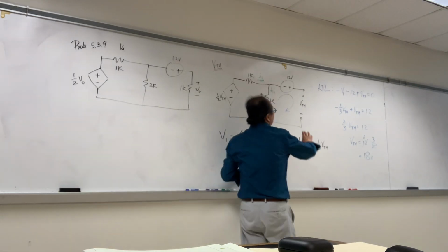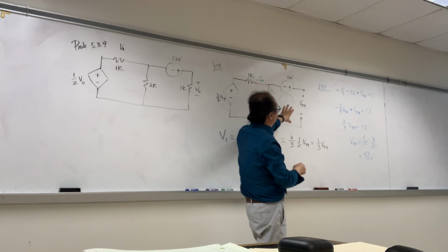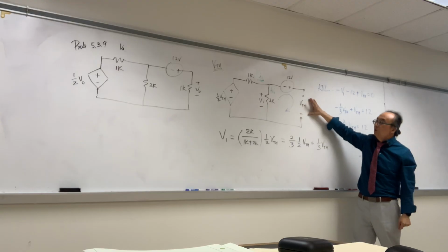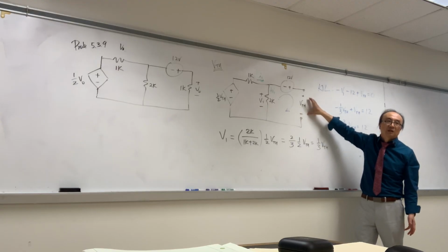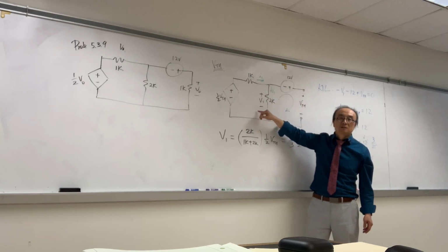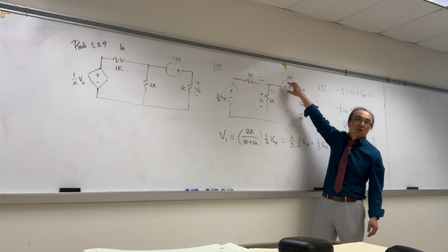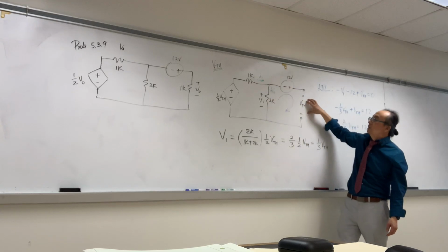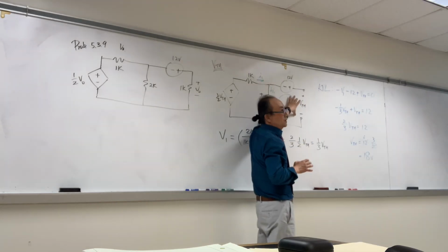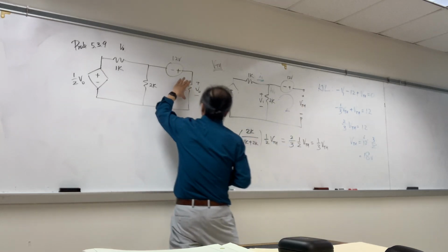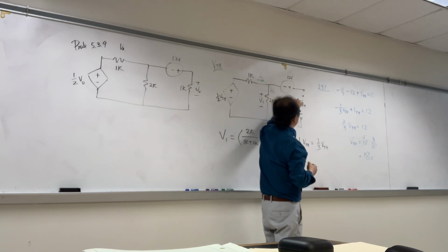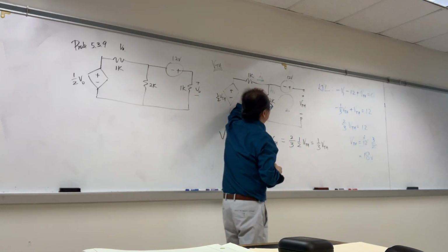Yeah, well, it looks like that, but it's not. Because when you deal with the VTH, we had the component in here and we took it out. So somehow we need to consider there is a voltage across here. So when we analyze this, finding V1 in this case, forget about this guy because there's no current going there. However, finding VTH, we need to keep it and analyze with other components. I'm going to say that again. When you take this load out, we end up getting this circuit. Since there is no current going there, VTH is parallel to V1.